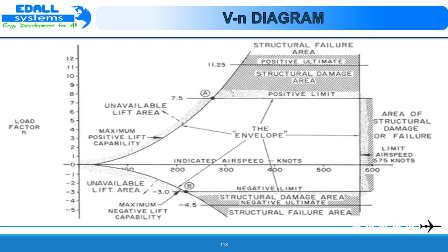The airspeed at this point is the minimum airspeed at which the limit load factor can be developed aerodynamically. Any airspeed greater than point A provides a positive lift capability sufficient to damage the airplane. Any airspeed less than point A does not provide positive lift capability sufficient to cause damage from excessive flight loads. The usual term given to the speed at point A is the maneuver speed, since consideration of subsonic aerodynamics would predict minimum usable turn radius to occur at this condition.